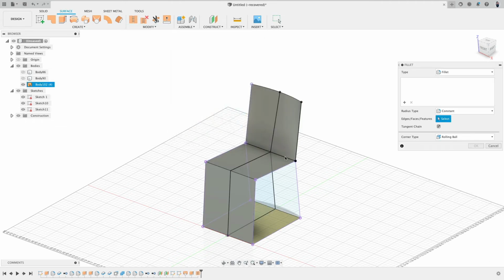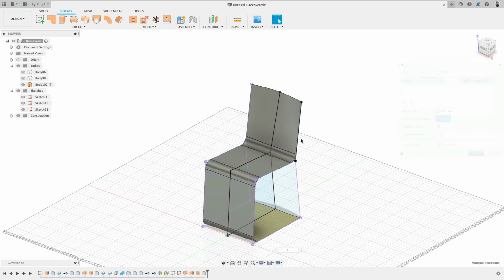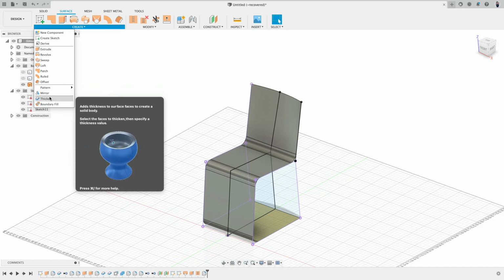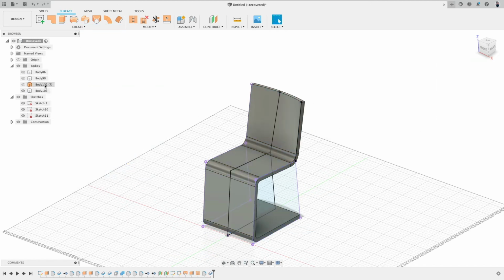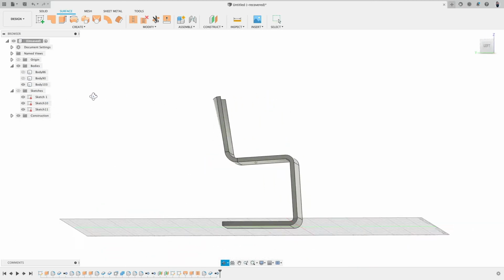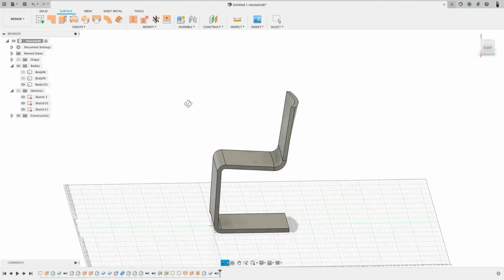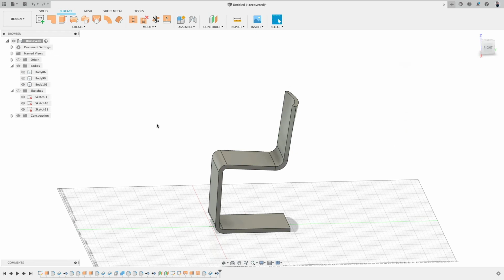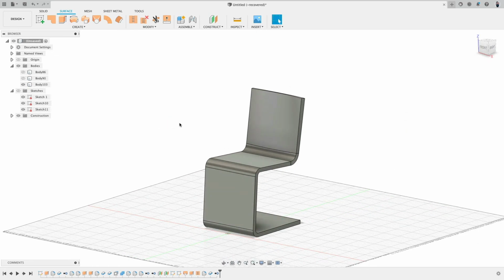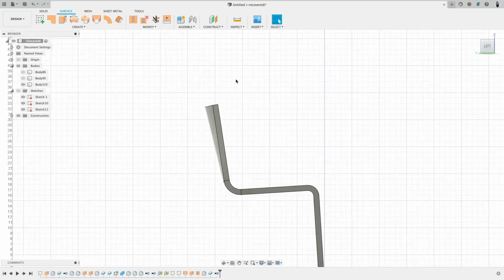Now we can go fillet, 2 inches, OK. And then create, thicken. There we are. This we can now remove. Yeah, look at that. No, that doesn't look too bad. Quite nice. We could go ahead and then round the edges, but we're not doing it in this case because we don't have the time for this, and there wouldn't be anything new you really would learn.